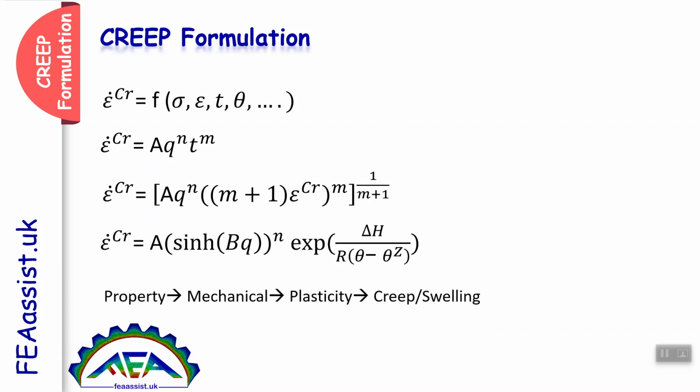You can go to Abaqus, go to Property, Mechanical section, Plasticity, and there you can see the Creep and Swelling option, and in that section you can enter all these parameters and predict the behavior. But mostly you cannot predict the experimental behaviors, and you cannot fit the experimental curves by these equations.